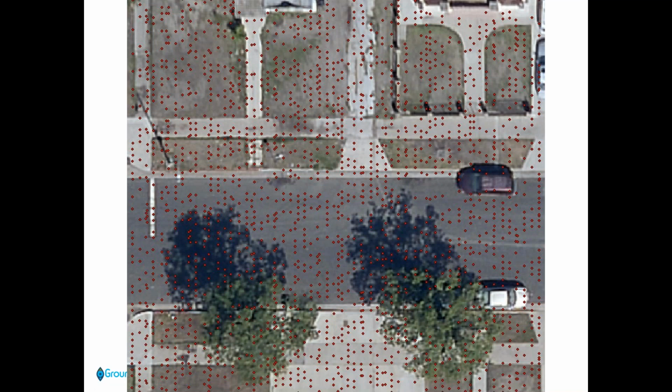One of the things that we get asked a lot about LiDAR data is, can you see the curbs? How exact do the curbs need to be? The surveyor would want to go out there and capture the top of curb along, if you can actually notice where the curb and gutter is in front of the car here, a surveyor would want to capture the top of curb and insert it as a break line. That's what we would expect. If you see where the curb line is, we would expect most of the flow to actually be in this gutter apron here. So we see this concrete gutter apron. Most of the flow actually is not on the curb, but it's in the gutter.